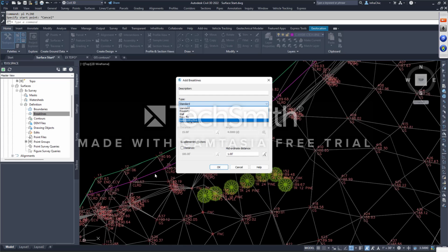If you do from bottom to top and every jiggity joggity is in there, then the top of the wall will reflect every jiggity joggity, okay, even though it's straight and flat. So there are a few minor issues using wall, but I still do use it. So just be aware of that. You can use break lines from a file, okay, and then of course there are non-destructive break lines.